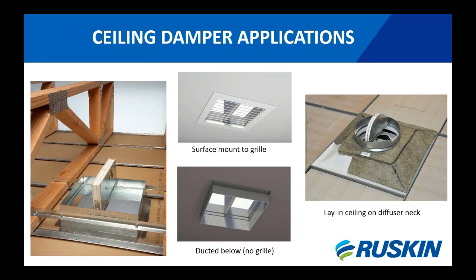All of those can be applied equally. So if you go in the UL directory and you find a suspended floor ceiling system, the lay-in type, if you see a damper depicted there, then these ceiling radiation dampers, what I would consider the standard type, can be applied on any of those particular designs. None of those will be wood construction. It's all made up of steel joist, concrete, steel decking, that type.